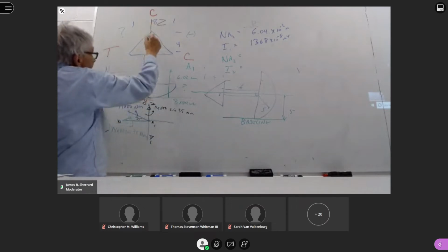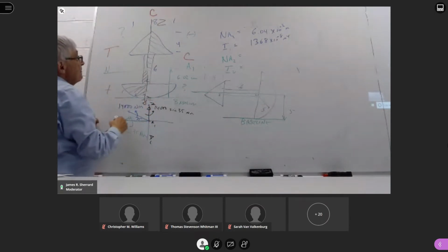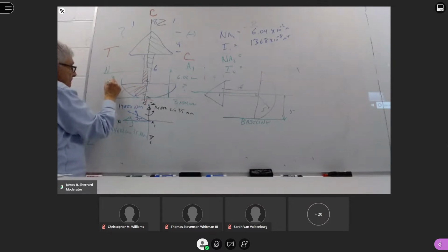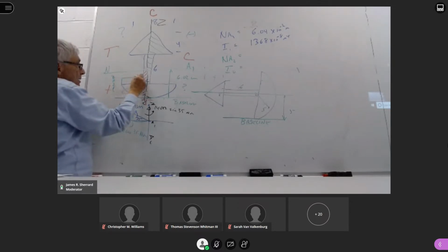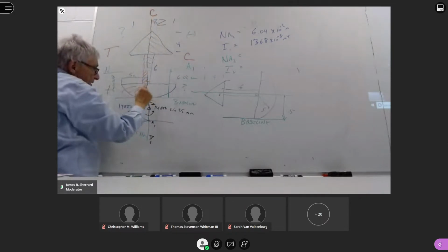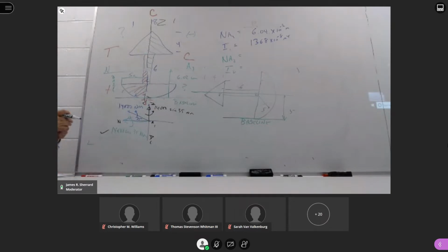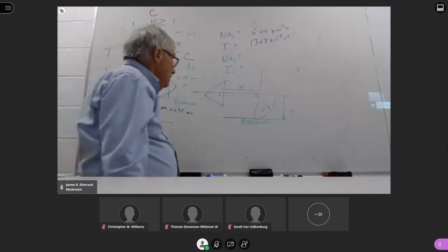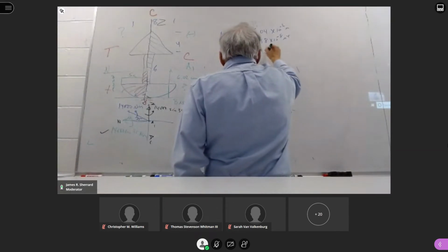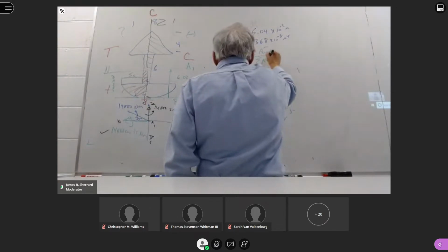So this neutral axis is from the baseline, 5 centimeters, to neutral axis 2. But you could also say, maybe I need to do this just for validation or to prove that I can calculate this. So I could look at the neutral axis as the sum of my areas times my centroids divided by the sum of areas.